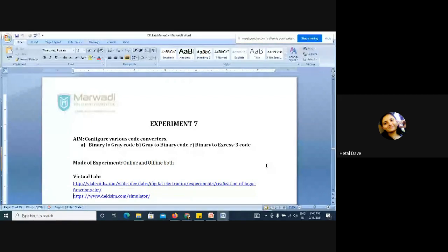Today you need to design it using AND gates. Whatever you are going to design today is available ready-made as decoder IC 74138. The internal of this IC you are going to design today. I hope you are getting my point. So start your work.